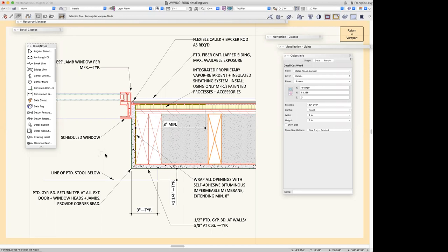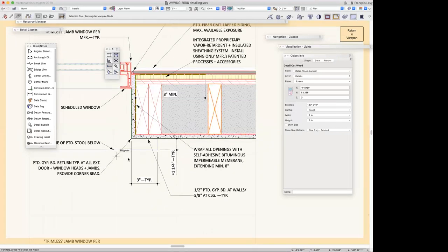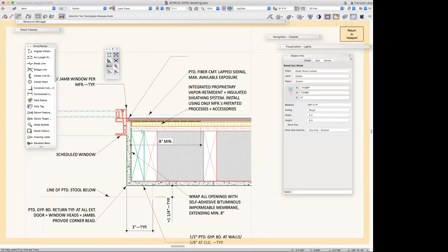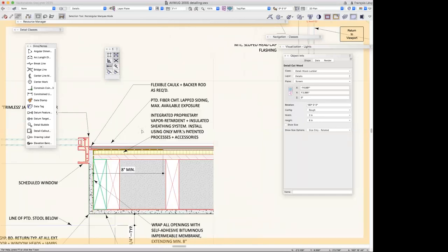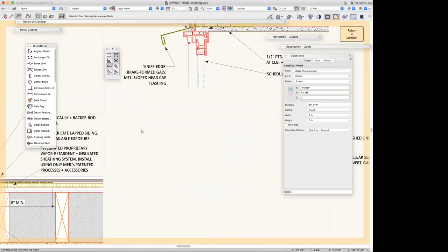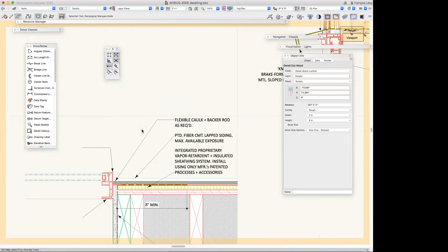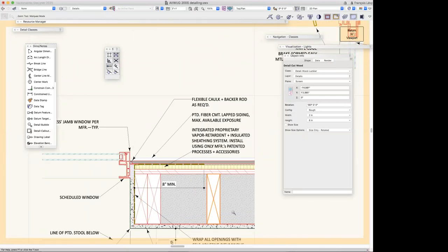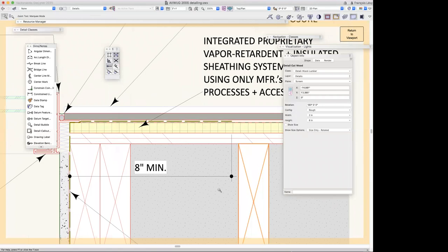Now, the other thing that's really key is that I use my constraints, or you can tell I'm kind of old school here, we just call them snaps now, right? So I've got my constraints, my grid snap, my object snap, snap to angles and objects and so forth. So that as I'm drawing, I'm trying to constrain everything and snap to it so that everything is nice and precise.